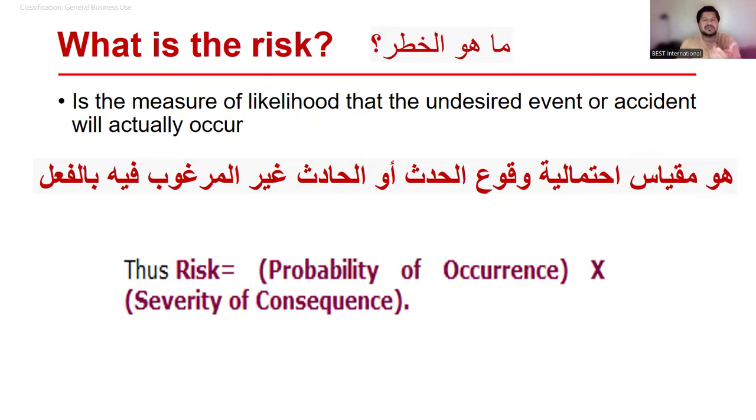If we don't follow the work permit system, we don't follow safety rules, the probability of accident in a hazardous area goes up, especially zone 0 or zone 20, or let's take an example of zones 1 and 2 as well, or 20, 21, or 22, in all areas with gases, vapors, or combustible dust. In both areas, consider the probability will go up because you are not respecting safety rules. You're not following the work permit system, or you're not doing any sort of risk assessment, or method statements are not there. The right team is not on board. Toolbox meetings you're not conducting. The right set of PPE is not there. So probability will go up, and you give the number 5 to probability.